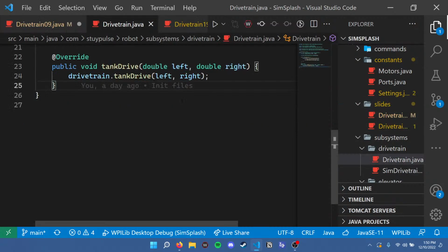Do you simulate a swerve drive? A swerve drive is much more complicated, and you can't use a differential drive sim like we did here. The way that we went about it is we simulated a bunch of individual motors using the flywheel sims that we talked about. For example, you could simulate the drive motor and the turn motor separately using flywheel sim, and put those together into a full swerve drive. I don't think my laptop can handle opening the swerve code, but you can take my word for it.